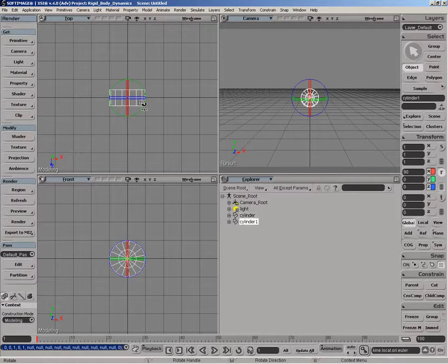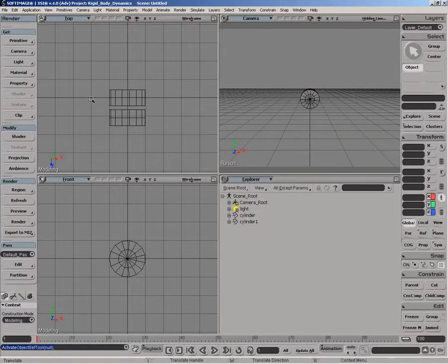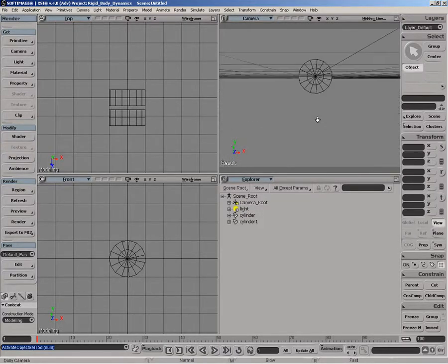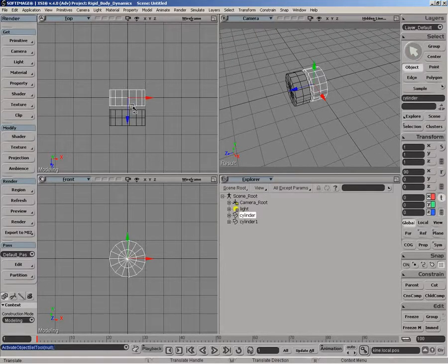We're going to make the destination object that's actually rotating by duplicating it and just translating it over slightly. Now, what I usually do is I'll build all my objects from my actual rigid body rig, and then afterwards apply the rigid body property and the constraint. So everything's positioned in its initial state first of all, and then the actual rigid body properties are applied. It just makes it a little easier to manage your scene and do things kind of in an orderly way. But for the sake of this example, I'll just go about and show you what each component's doing, so you have a good idea of how the actual mechanism of the rigid body works.